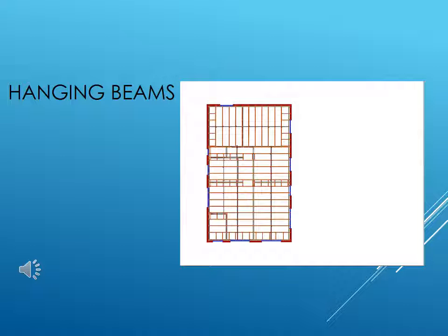The other hanging beams basically split each room into two equally wherever possible, and in this case we have a very simple wall frame layout, and so you will notice that everything there is parallel, and when you increase the size of this drawing, you'll even see where I've put in the soldiers which actually connect the hanging beams to the ceiling joist.